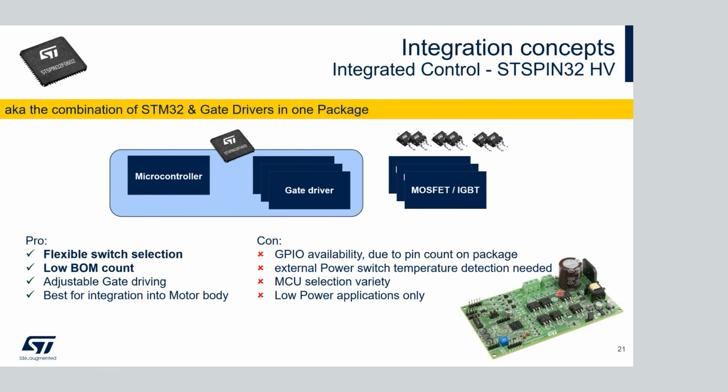and due to the discrete packages, you do not have any inside temperature detection, right? So you have an external temperature detection need on the heatsink or near the PCB, near the device, in order to see how the temperature is in your power switches. And you do not have the same amount of microcontroller variants available as STMicroelectronics offers in the standalone microcontrollers. At the end, we can say that this kind of integration with the discrete switches is more related to low power applications, for in motor low power applications.